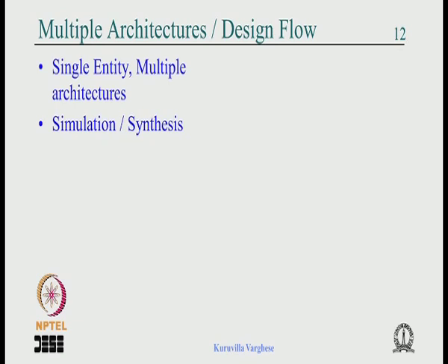Definitely one can think of it like this: you can have an architecture for simulation. As I said at the beginning, anything you write using the VHDL syntax can be simulated. If you know the syntax of VHDL, you write any code, you go to the simulator, and whatever you have written can be simulated, but unless you take care it may not be synthesizable. So these two are different games altogether.